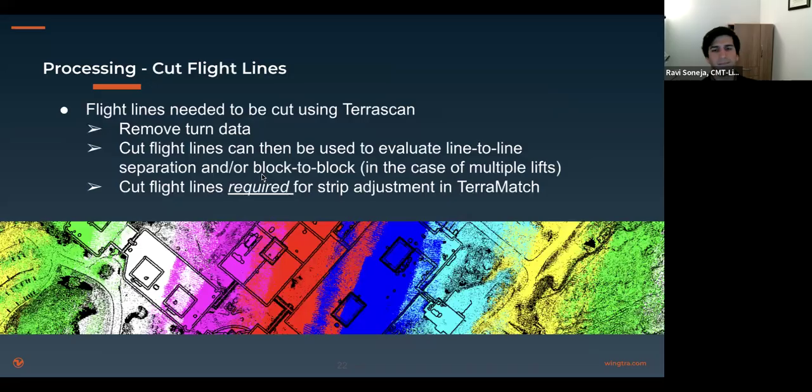Yeah, obviously we've got a base station running on site locally, so that data is being processed in-house. I think a Trimble R12 was used as the base station. Wingtra has pre-processing software that comes with the system, which can be used for the initial pre-processing to take your raw laser information and generate a point cloud. From there, we go into a TerraScan or TerraSolid environment.